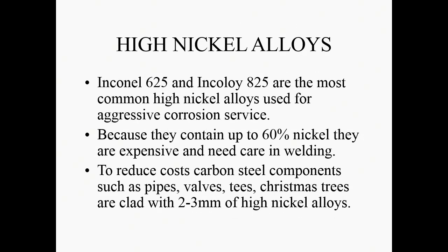What happens if you have a material that has to go in a very, very aggressive environment, very high content of sulfur, let's say? Well, then you go to another alloy system. You replace the iron in your alloy with nickel. And there are two alloys, Inconel and Incoloy, which are commonly used for the most aggressive corrosion surface.